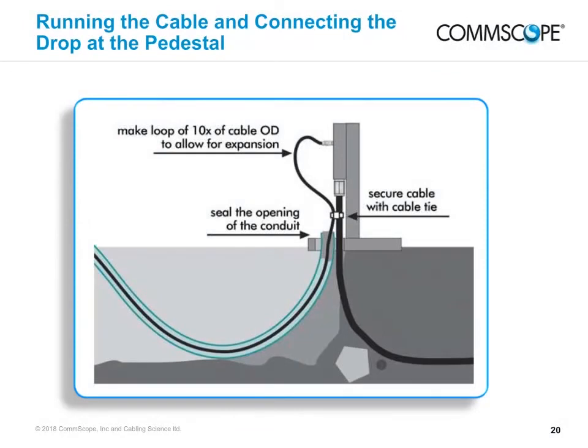If you are plowing in the cable or CIC, make sure you have dug a receiving trench to the attachment point of the residence. Run the plow along your planned route to the attachment point. Remember that for NEC 830 considerations, cable not in conduit must be buried at a depth of 18 inches or 45 centimeters. You may not be able to run the tractor directly to the attachment point. If not, dig a larger receiving pit.